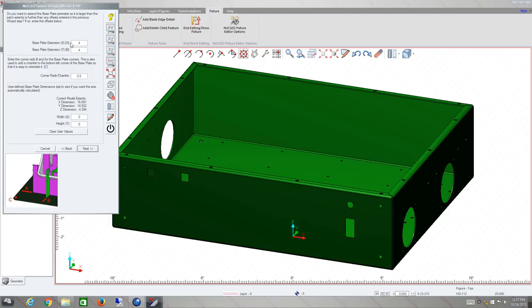On this page we do the base plate, how much bigger the base plate needs to be. We were saying 4 inches bigger, so it's bigger than 4 inches in the extent of the part. We put some radiuses on the corner. On the bottom left we put a chamfer of the same value, so you know where the bottom left is. And then in this field here, if you have a rotary axis, your head and tail stock arrangement, you can put in the dimensions of your head and tail stock, so the base plate fits the limitations of that rotary axis.